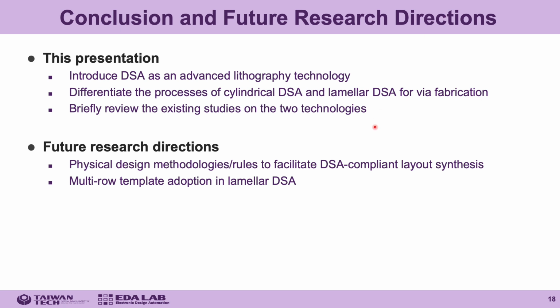To facilitate DSA-compliant layout synthesis, design methodologies or even design rules are required to be further developed. And for lamellar DSA, multi-row templates can also be adopted to further enhance the design flexibility of guiding templates, which can serve as future research directions.